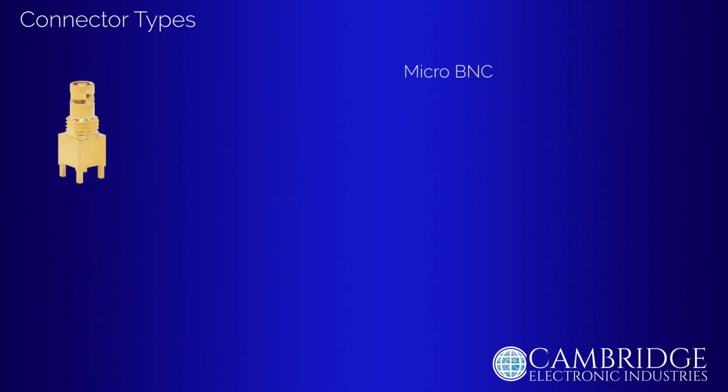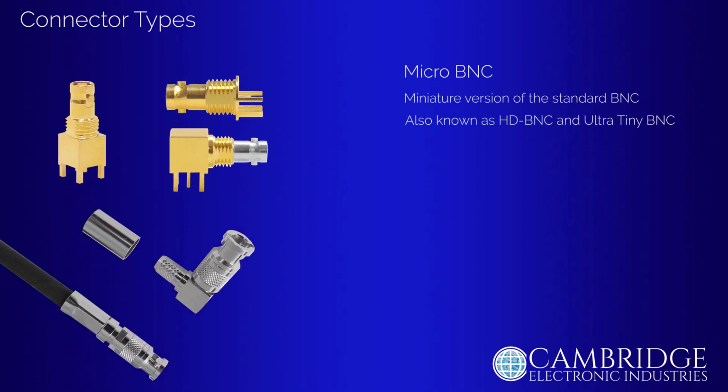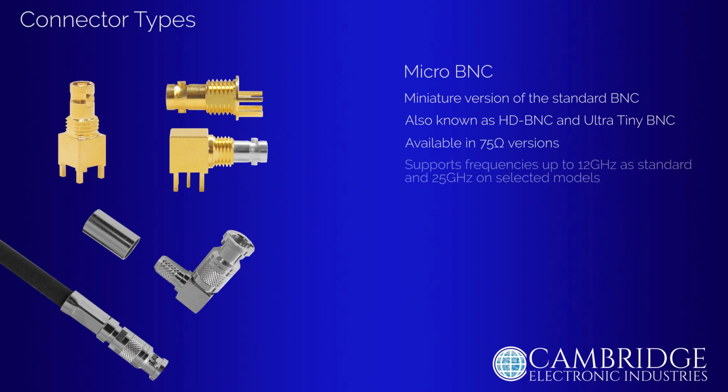The micro BNC connector is a miniaturized version of the standard BNC and is also referred to as the HD BNC or ultra tiny BNC. At 51% smaller than the standard BNC, it is designed for high density applications. These connectors are available in 75 ohm options, supporting frequencies up to 12 GHz as standard and up to 25 GHz on selected models.